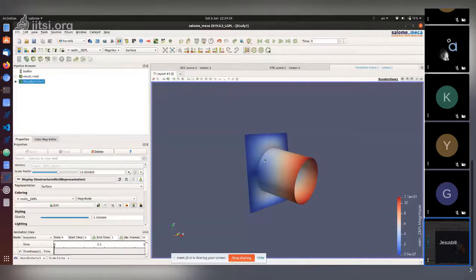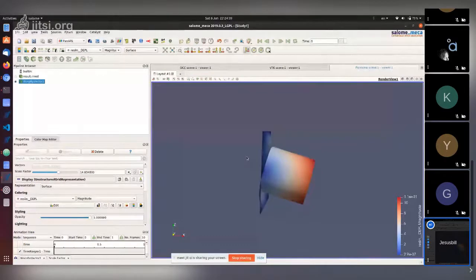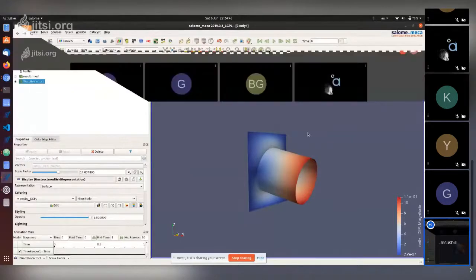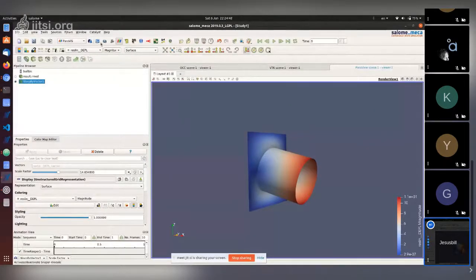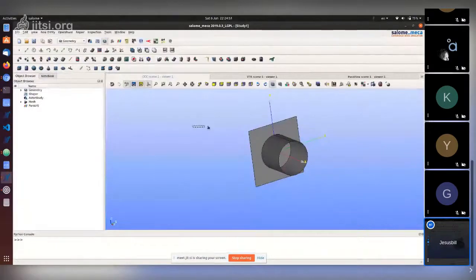A lot of things are feasible, although a little bit complex. I guess you would need a solid geometry, and then it depends what you want to do. I mean, if you have the parts that I created in the beginning, if you have more parts, as long as you do a partition, then everything is bonded together, and if you are modeling also the welding, you can see the stresses in the welding and so on.